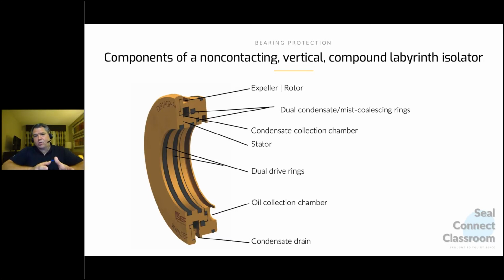But those are very visible. You can see what's going on. And by the way, if it's changing color, it's actually doing a good thing. You'd much rather the breather change color than the moisture get into your machine. There are ways to maybe move the breather and create a snorkel, get it away from maybe high steam areas or something like that. But breathers are good.